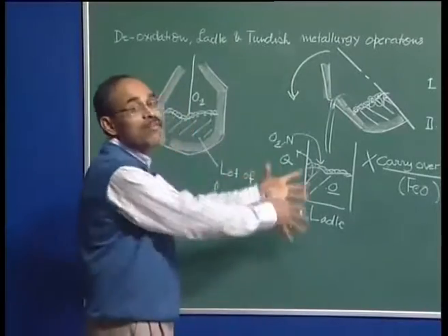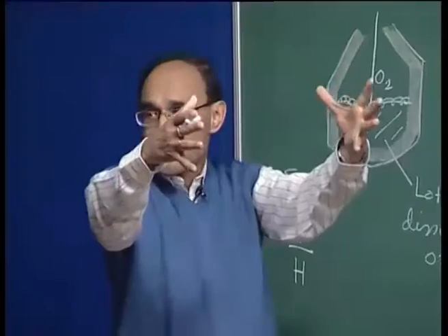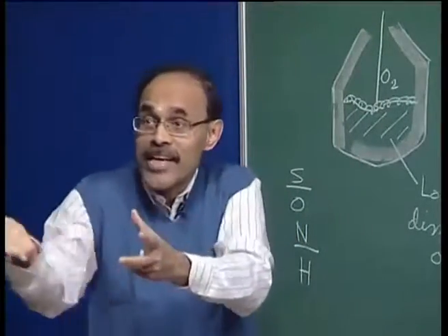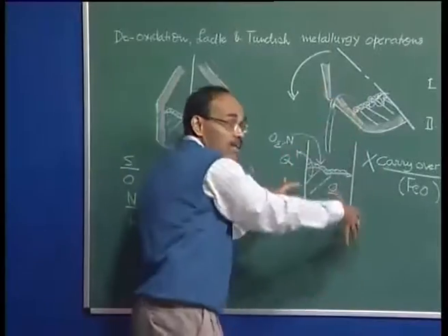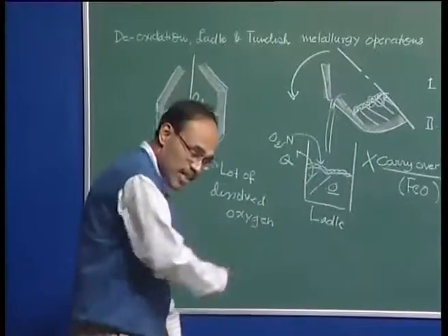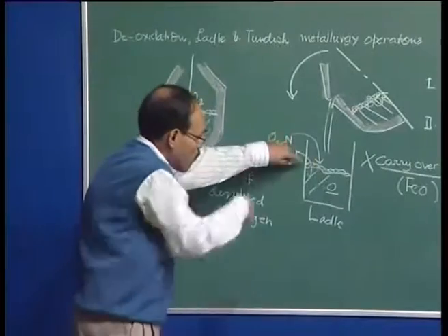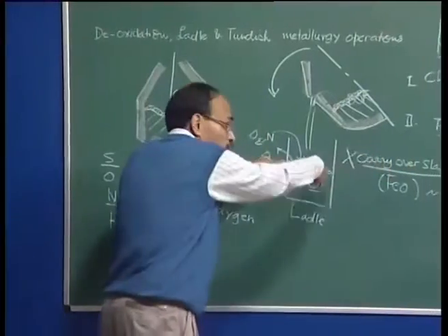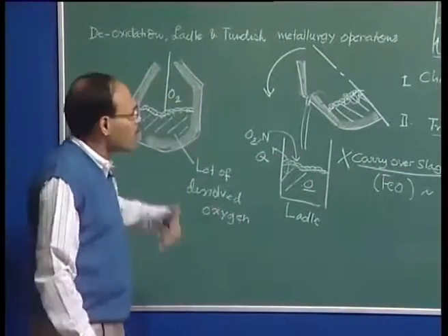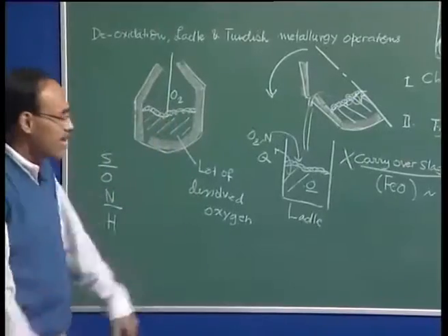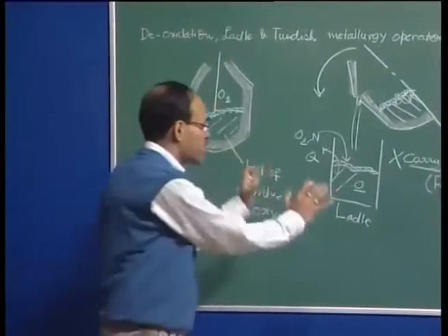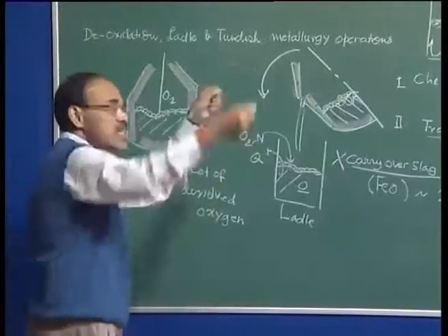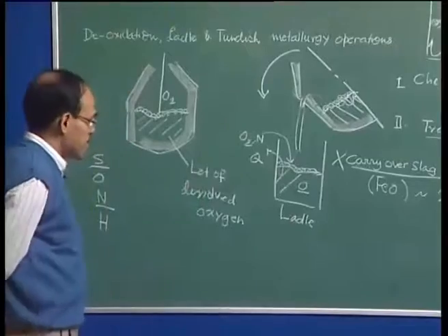And finally, the ladle will be placed over the turret in the continuous casting mill, where it is going to be cast. And as the ladle over the continuous casting mold is emptied, it is going to be recycled back and brought under the primary steel making furnace, and this is called the recycling of the ladle. From here it goes to the continuous casting bay, and from the continuous casting bay an empty ladle comes, and so a ladle is going to be used for a number of hits before relining is going to be necessary. But typically we must understand that the capacity of the ladle and capacity of the furnace are going to be identical. One hit is going to be poured in one single ladle itself.